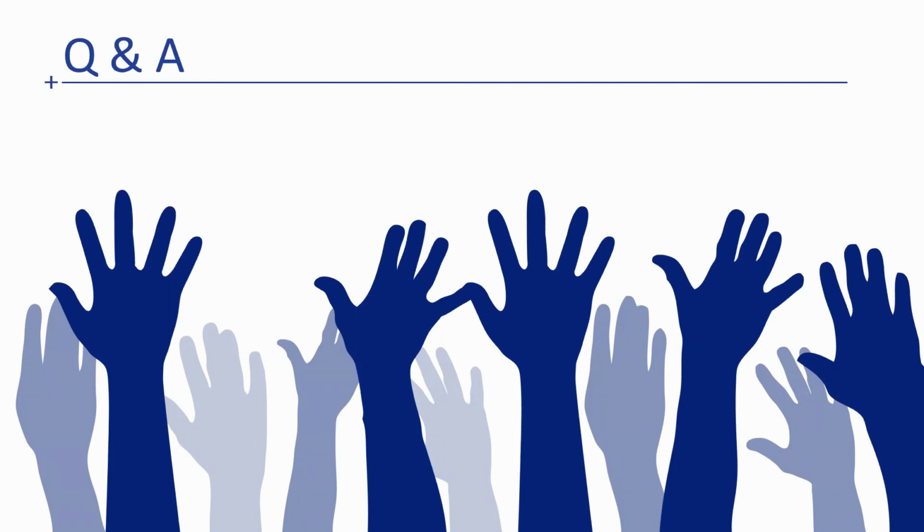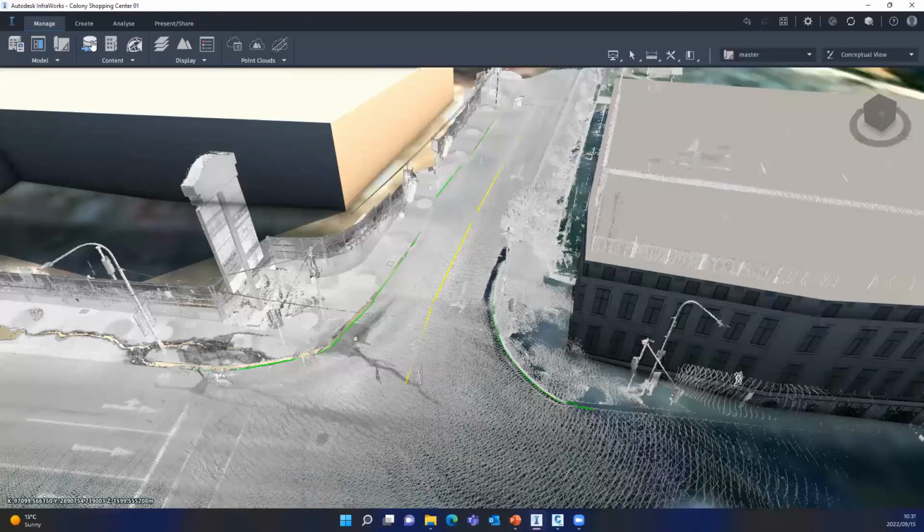Okay, another question here from Nigel. Can the mesh be imported to further create renders for visualization? It most definitely can. So what you can also do is, after creating these meshes, you can take those meshes over to software like 3ds Max, basically any visualization software, and you can then perform some actions on it, clean it up, make it look nice, and you can actually import those objects to InfraWorks itself to further your visualization process here.